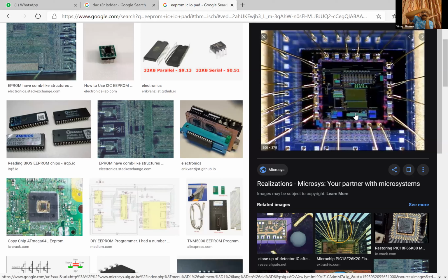Soldering each IO pad, hot soldering like this. So how accurately your machine can move, and how accurately it can solder the center point of each IO pad. Based on that, the dimension of the IO pad is given. Okay, generally it is in microns and big in size as compared to your chip design. They're quite big in size, okay, so that the machines can solder it.